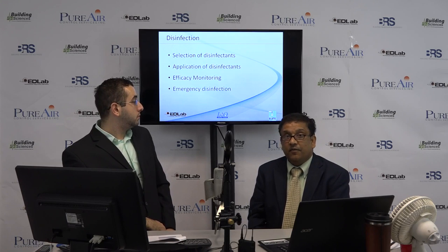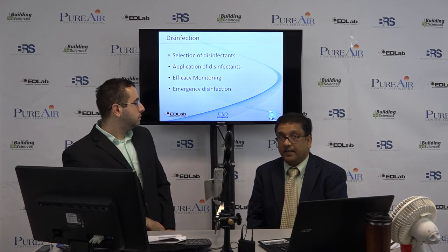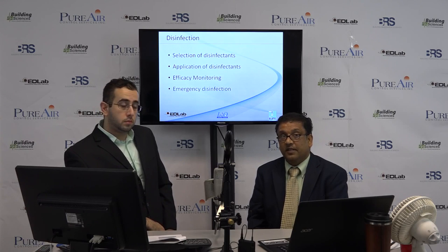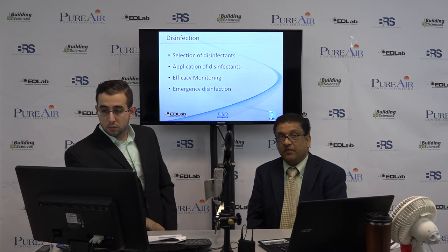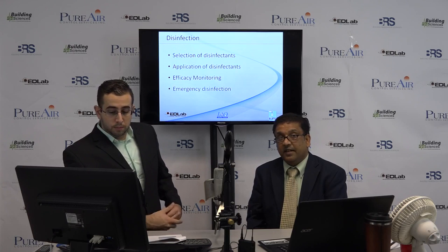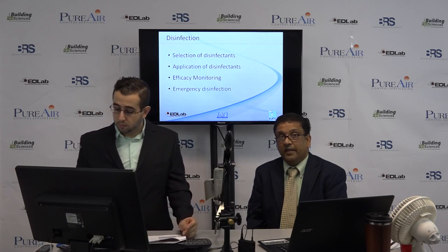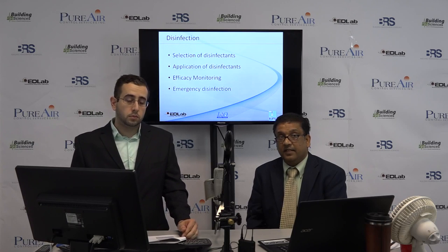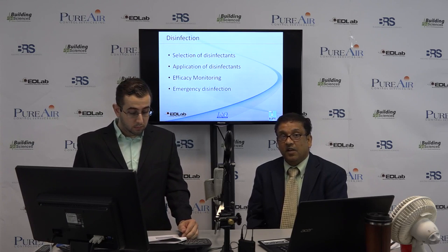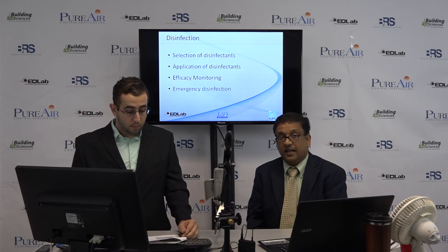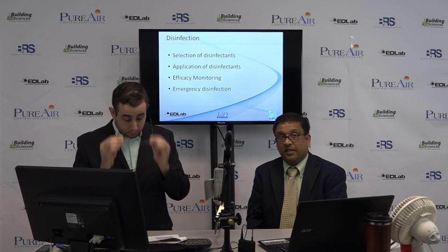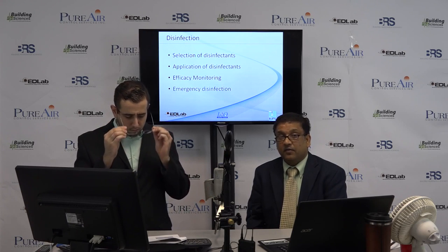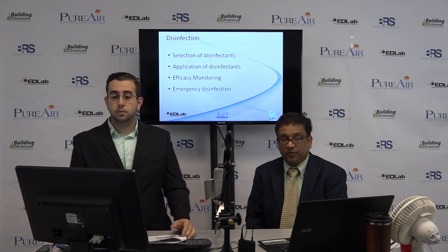Sometimes a situation comes when you have to do an emergency disinfection. Again, it should be performed as per the guideline made by the manufacturer of those disinfecting techniques, either chemical or physical, but it should be put in place immediately when an emergency arises. When I say emergency, I mean when you have a proven case and a proven source of bacteria, and for sure that particular hotel or tower or whatever is contaminated with this bacteria, then the disinfection should be taken immediately and addressed in that way.